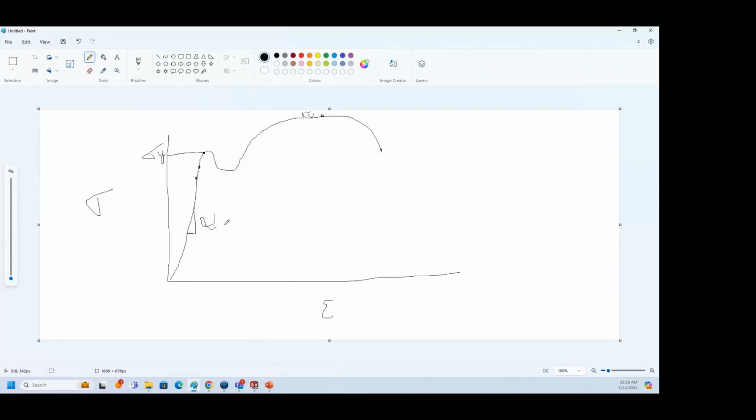where stress is directly proportional to your strain. So this is your Young's modulus value E. Every material for your linear static analysis needs these parameters: Young's modulus, sigma y, I will tell why you need sigma y, and the Poisson's ratio, that is basically your lateral strain to longitudinal strain, how the deformation is going to happen, and the density of the material.